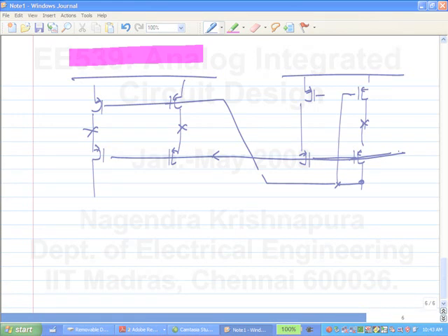That will worsen the differential response to some extent. So when you are designing a fully differential op-amp, you will design both this and this together, so you will have to iterate to get the best possible speed for the differential path. But yes, maybe if you had an ideal common mode feedback circuit, you will get a higher speed. That's possible.